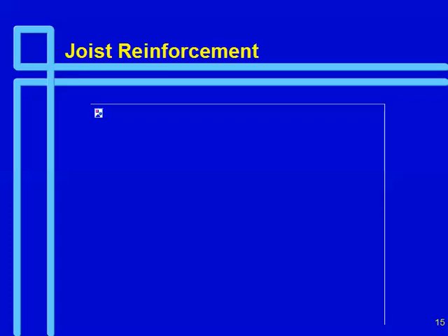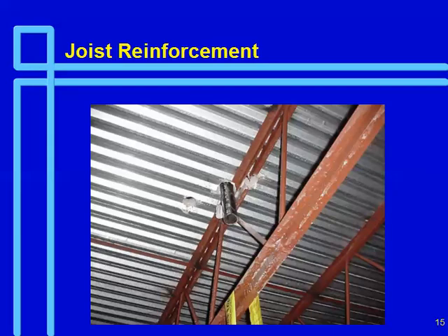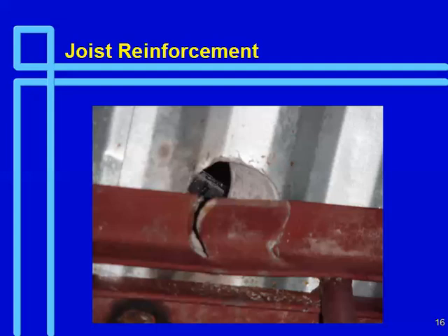Here's some cute pictures on joist reinforcement now. Here the plumber, he missed over here, so he went over here, and I think the next picture shows it better. This one, it cut most of the top chord, got down to this point, and I showed this the first time, and Larry Kloiber was sitting there. And I said, well, he didn't go all the way through the chord. And Larry said, yeah, it's probably because he ran out of drill, that they didn't go all the way through. But obviously that joist needs to be reinforced.